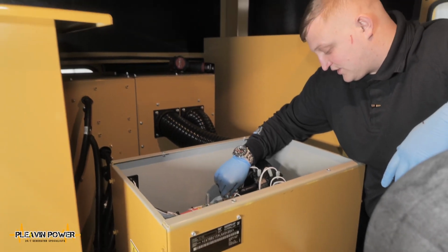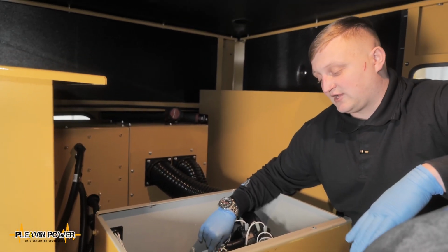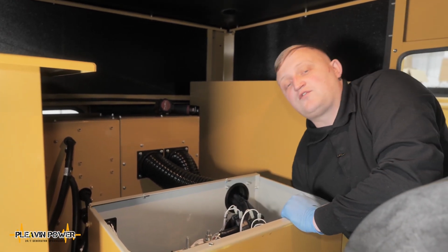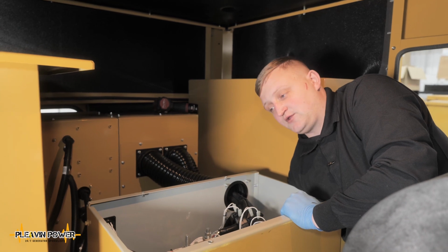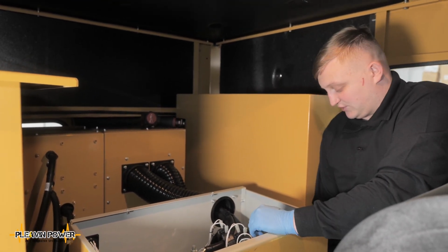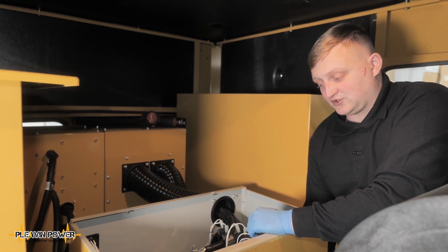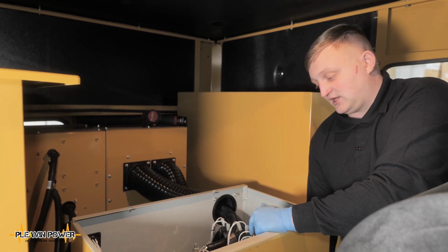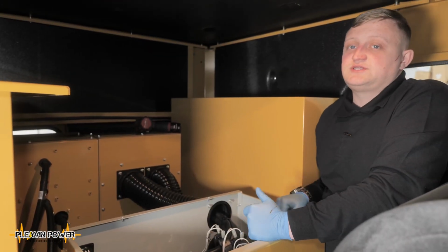That is the majority of the service checks that you will carry out. You would also normally inspect, although we can't show you on this video, the rear of the windings via the inspection chamber at the back of the alternator. However, you can't do it because of these air louvers in this application, but you would look up, visually inspect the windings and make sure there are no obstructions and that the windings are nice and clean and not suffering any debris entry. That concludes alternator maintenance for now.